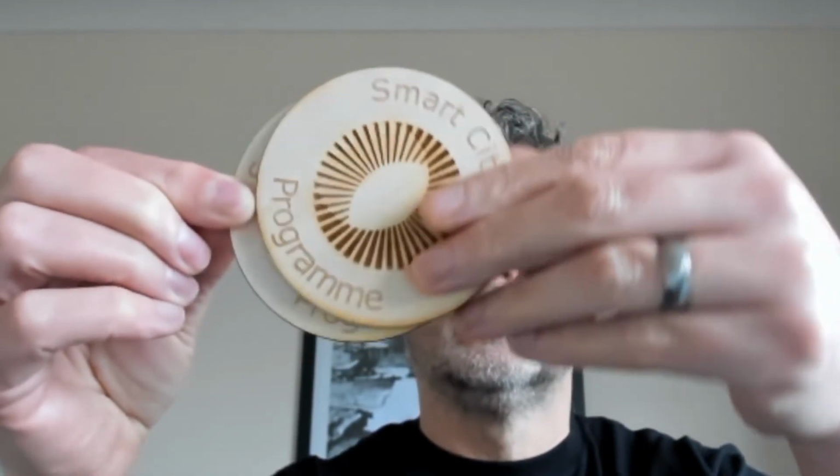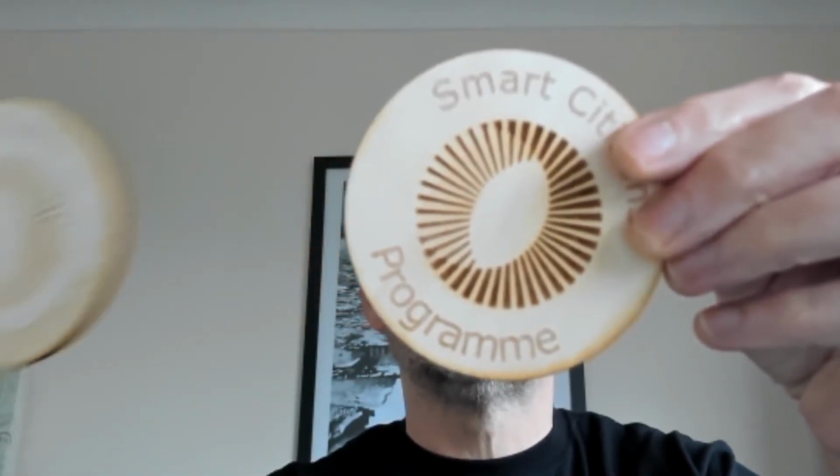It's quite light. This was 300 speed and about 35% power. And as you can see, this one is much darker. What I did is I just put it as a different setting. So I just changed that one then to 300 speed the same, but the power I moved up to about 45, 50, something like that, just to get that a little bit darker. So really the speed and power becomes an aesthetic choice, which is quite interesting.